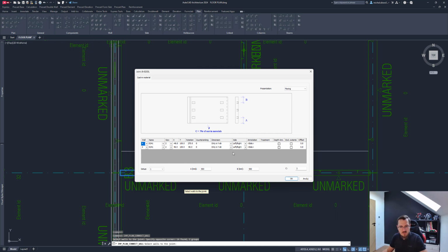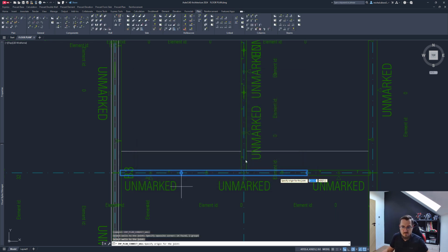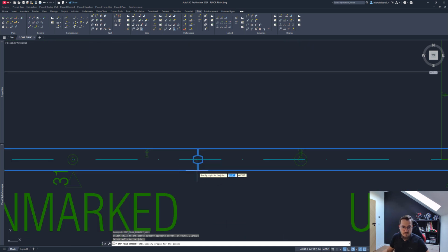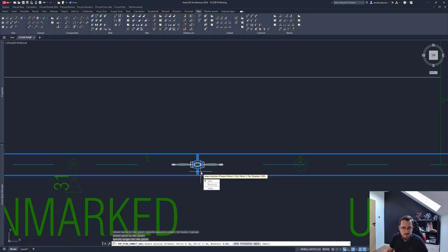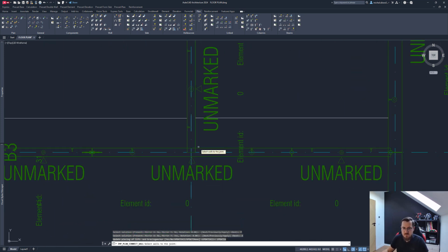And here now I can specify the distance, the type of setup of the casting materials on the side of my wall. So I can, for example, increase the number of casting materials in this connection. Okay, and I've now applied the casting material, and I can swap the sides, or if there's a different alignment possible, it will suggest it here. There won't really be a better alignment here, so I'll just apply and update all. So this will also update the lifts and the geometry.